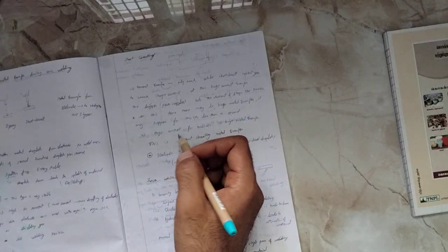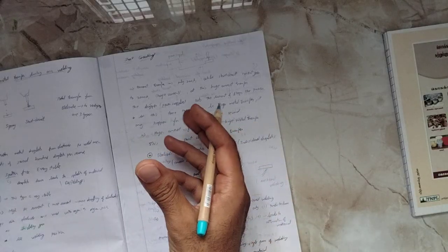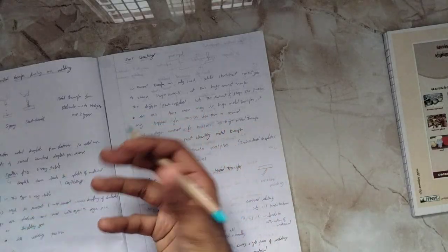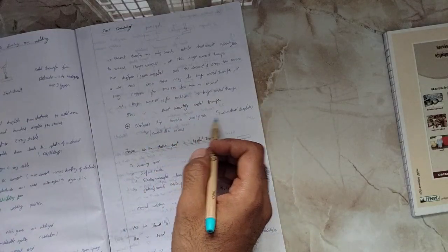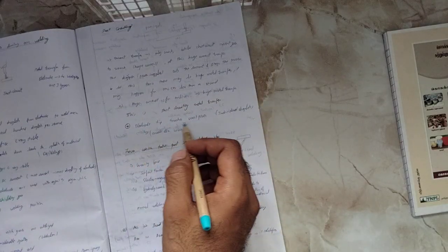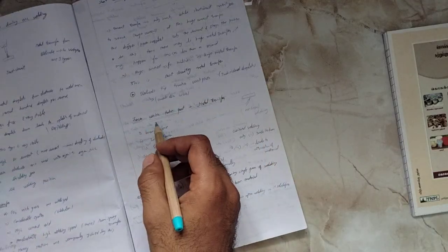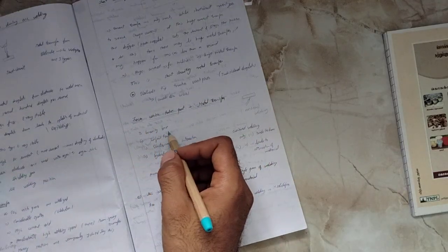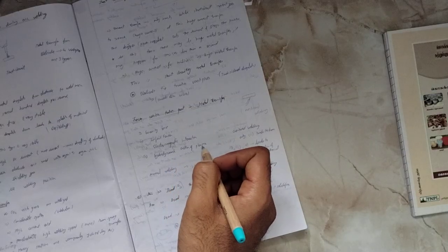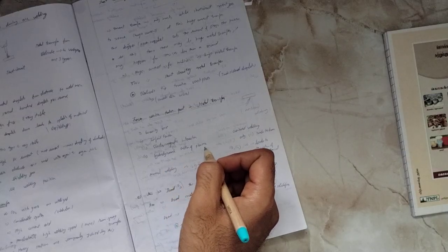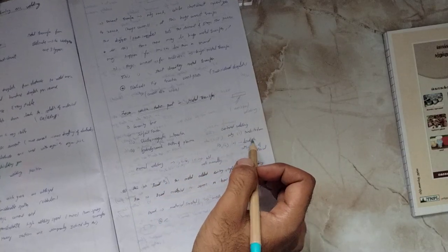So that is called short circuiting. Due to the short circuiting, we are transferring a lot of material within a short duration of time. The electrode tip touches the individual workpiece. The forces which take place in the metal transfer are gravity force, surface tension force, electromagnetic force, and hydrodynamic action of plasma.